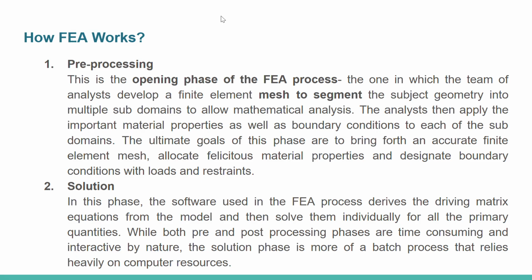The analysts then apply the important material properties as well as boundary conditions to each of the subdomains. The ultimate goal of this phase is to bring forth an accurate finite element mesh, allocate appropriate material properties, and designate boundary conditions with loads and restraints.